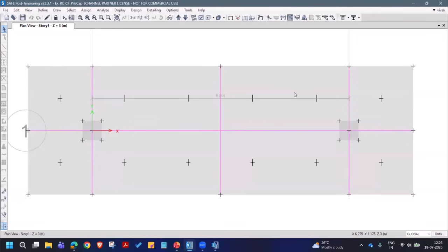Some people will tend to have a conservative estimate of these forces and the design, so they can have 1 meter strips across. That is going to give you a conservative design of reinforcements as well. But since those things are arbitrary, I'm going to leave it to you.